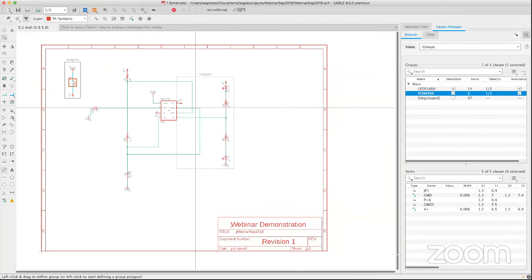If it's only values, well, first of all, the easiest way to take care of that is to delete the board and push a brand new one from the schematic, okay? That takes care of that really fast, but you lose your entire layout. So it may not always be the solution. If it's only values that you're having issues with, you could just change the values either in the schematic or on the board. That way they become consistent.